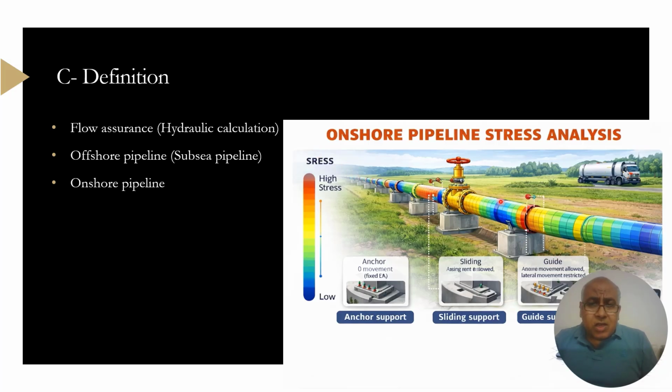Then, in the model run itself, we put in all the data that we discussed: the temperature, the internal pressure, the wind effect, the seismic effect, the loads that we have, and the weight of concentrated items like valves and so on, according to the mode of operation. Then we go through the design of the pipeline as we mentioned.